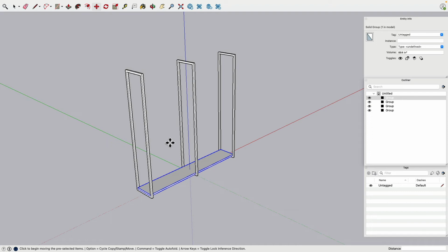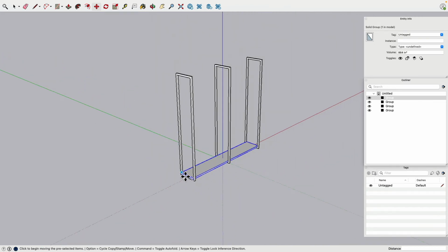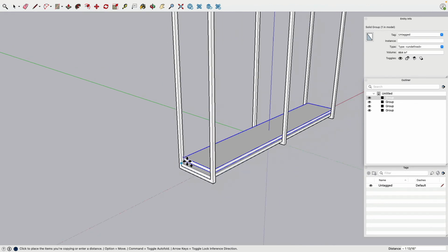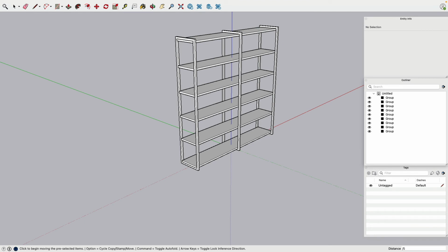Here, SketchUp is actually brilliant. So this corner point I line up with there. So move and copy. Bring this to there, click, and now here comes the trick. I'm now typing in divide by 5. And look, now I have 4 more pieces in between.